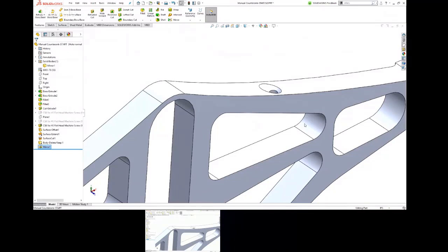subtraction. How does it know that's a full feature? It doesn't. The drawing doesn't know that. So I do have to put a 2X on there on my drawing, but that's the only thing I have to babysit. I have an accurate hole call out, which is really the reason that I went this direction in the first place, as opposed to just doing a revolved